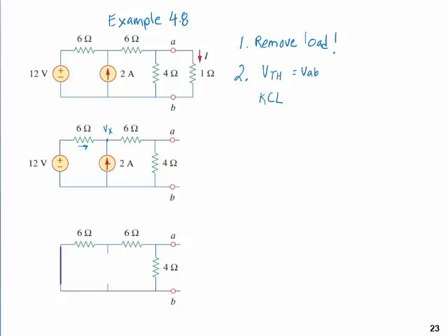I'm going to assume a current this way, this current goes this way, so that's two ends. I'm going to call this the out current there. So I1, I2, and of course I2 is the same current that's right there. So let's do KCL at the node at Vx. So I know there's 12 volts right here. Here I'm going to call my reference 0 place. I'm going to put my polarity markers on everything. Current going in is at a higher potential here than when the current comes out. Okay, so we'll do KCL at that node.